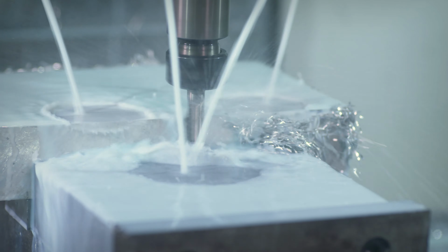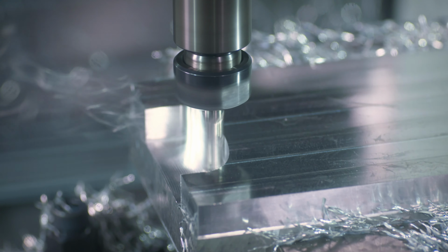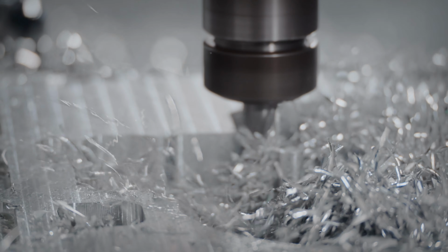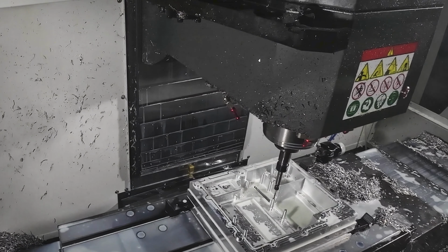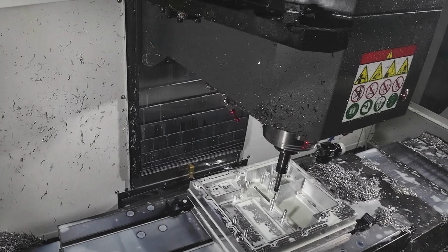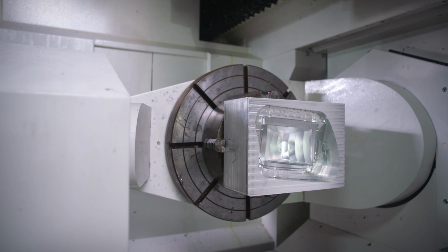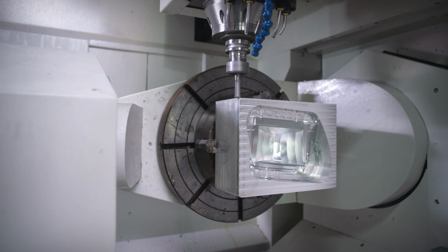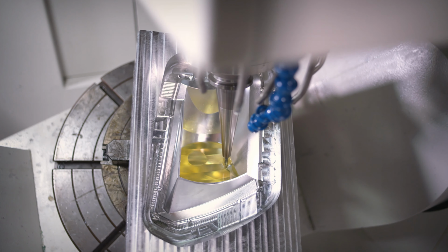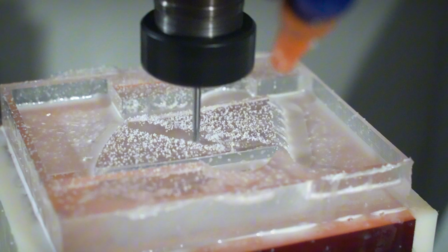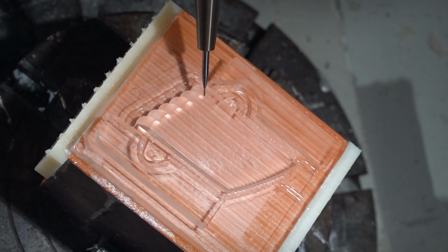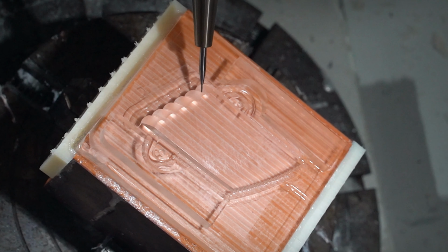The structure of the part also determines which type of machine we need to use for machining. The 3-axis machine is the most basic equipment, ideal for handling simple geometric shapes, and is cost-effective. However, if the part has a complex geometry or requires high-precision continuous surface machining, the 5-axis machine becomes essential. But keep in mind that the cost of 5-axis machining is about 3 times higher than 3-axis machining. So, to save costs, it's best to simplify the part structure as much as possible.